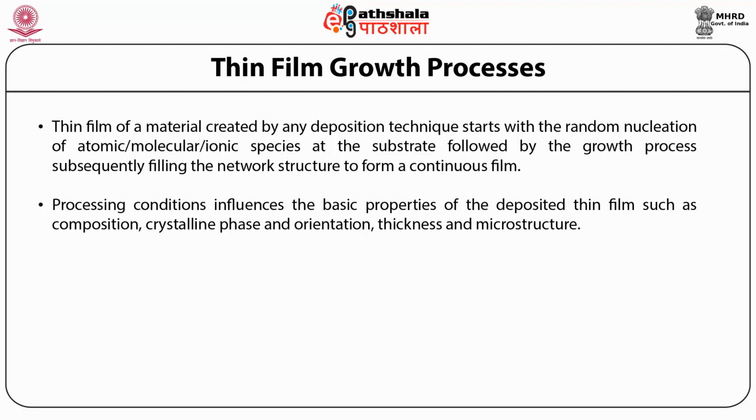Crystallization of the thin film occurs during the coalescence stage, and the crystallographic orientation and grain size depend upon the nucleation density, which in turn is determined by the surface mobility, processing time, thermal treatment, and kinetic energy of the arriving species.